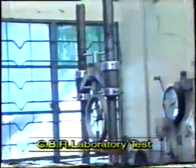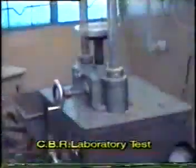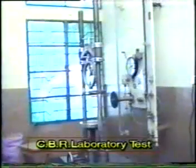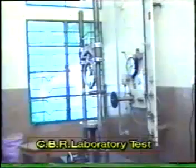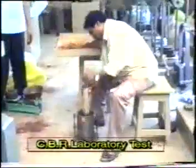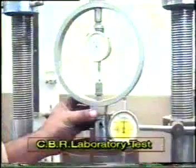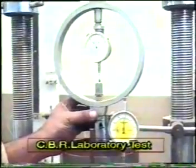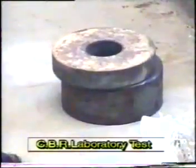Now let us see the laboratory method of determining the CBR value for a given pavement material. Apparatus: loading machine, cylindrical molds, compaction hammer, adjustable stem with perforated plate, tripod dial gauge, annular weight.